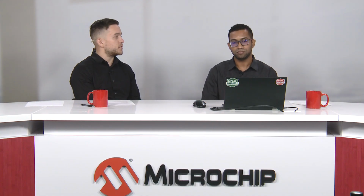Okay, and what's under the hood of the simulator? Good question. I will be taking the audience through a couple of simulations today, so we will get a look at it firsthand. Before we dive into it, let me speak to that a little bit. The Mindi simulator is made up of 2 different engines, SIMetrix and SIMPLIS. SIMetrix is a classic SPICE engine that can be used for general mixed signal and analog designs. SIMPLIS, on the other hand, is more geared towards switch mode power supply designs. It uses piecewise linear models of switching circuits, which results in simulations being completed significantly faster compared to the classic SPICE engines. Awesome, thanks for explaining that to me, MD.